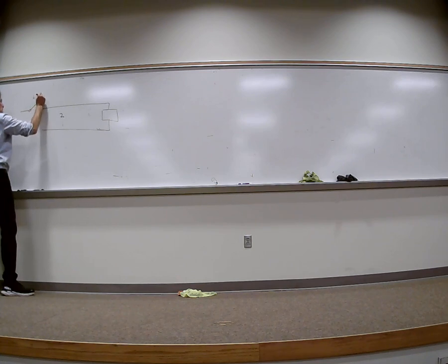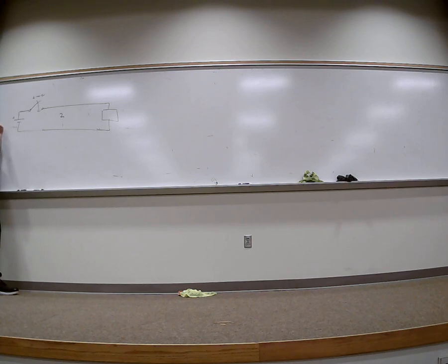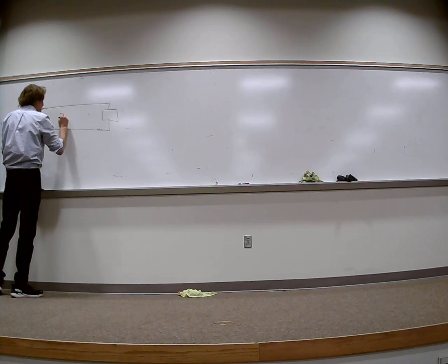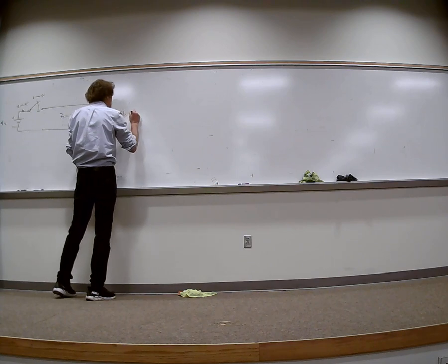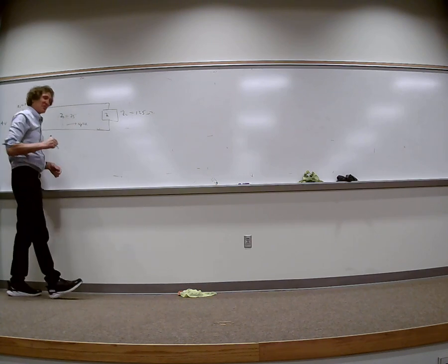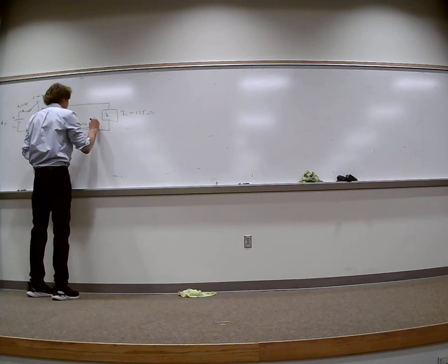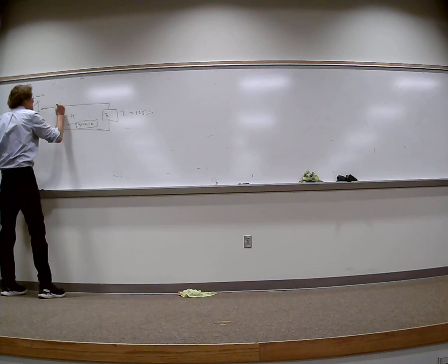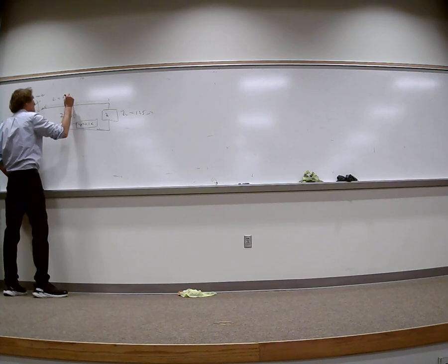All right, hold it. Let me get this drawn up. What's the battery? 4 volts. And RS is 25 ohms. Z naught is 75 ohms. The load here is 125, so Z equals 125. The propagation velocity is 0.1 C, so it's only a tenth of C. And the length of the line is 6 centimeters.